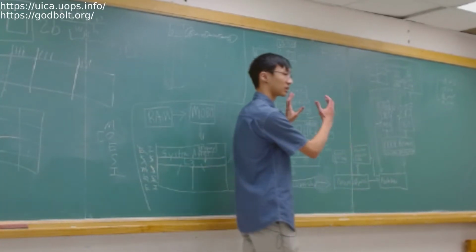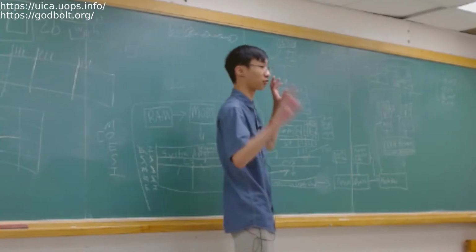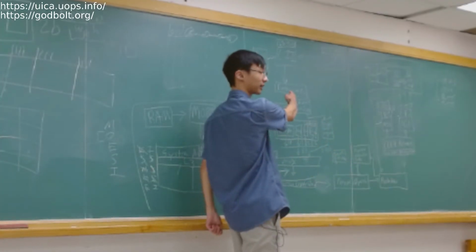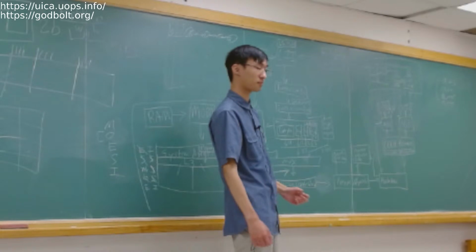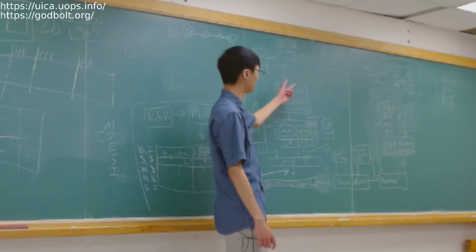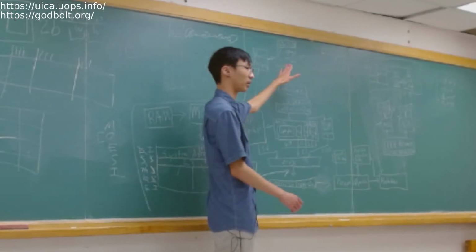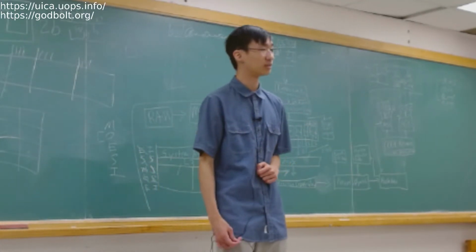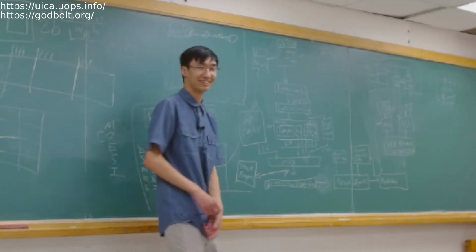So during this stage, you will get one thread running on the instruction fetch, and the next clock, a different thread will be running on the instruction fetch, and you'll have two threads. They'll alternate for each of these sections here, and when one of them's off, the other just flows through all of them. It's completely normal, except some things are duplicated and some things are magic.